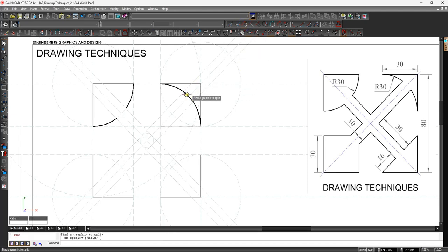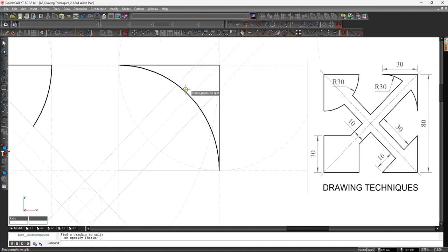Now on paper you would just not have drawn in that solid part, or you can erase it afterwards, but then it's always better just to draw it up to where you need on paper. Here on CAD I'm going to zoom in, and select the arc that I want to erase, create the reference point where I want to cut it off, again select the line that I want to erase and click the reference point that I want to delete, and then with the selected tool active I'm going to select that part of the line and delete that, and that will give me the desired result.